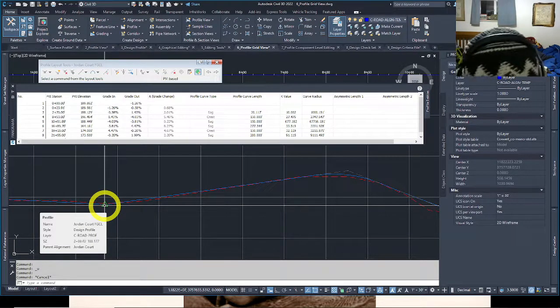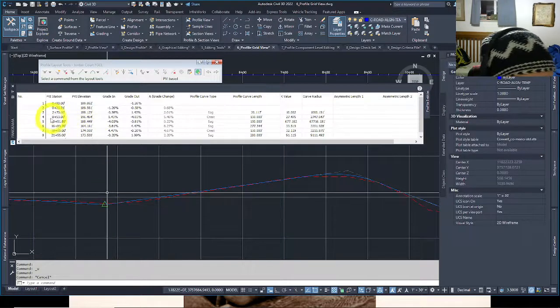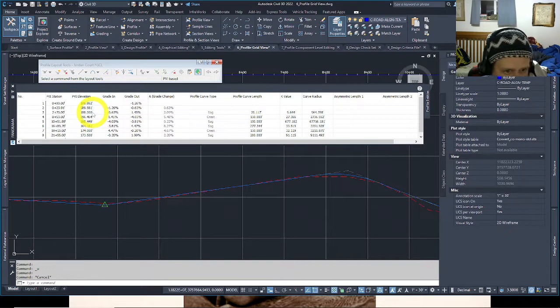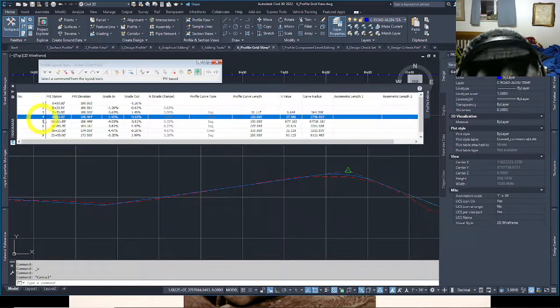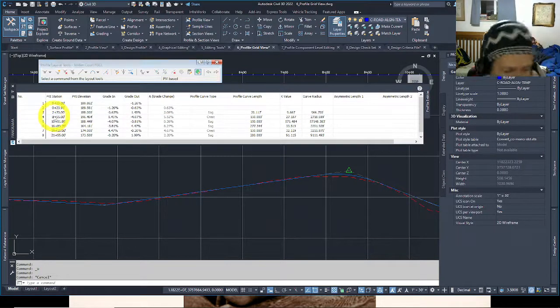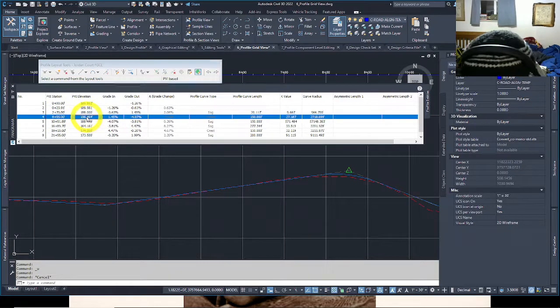And the PVI value of an elevation of this same one, we're going to change this to an even elevation. So this is where you're going to do your fine tuning of your profile view, getting it to even stations, even elevations, and various things. So it wants us to change a few more things. Item 4 wants us to change this to 855 and even 5-foot stationing. I can tell you, for example, and the elevation to something a little more even,